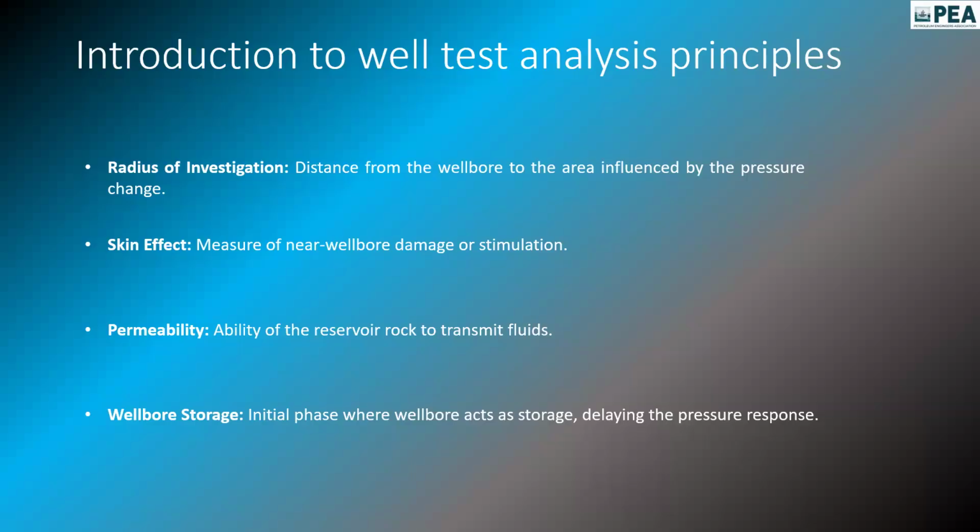So here, what happens is the wellbore acts like a tank where it holds some fluids. Generally, before production, we do some operations. You might have drilled a well, set casing, and sent some drilling fluids. These drilling fluids reach the bottom and start moving from subsurface to surface through the annulus space.